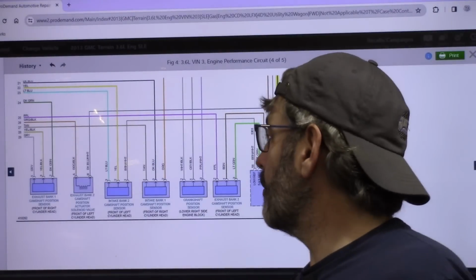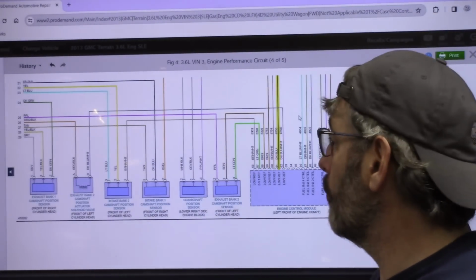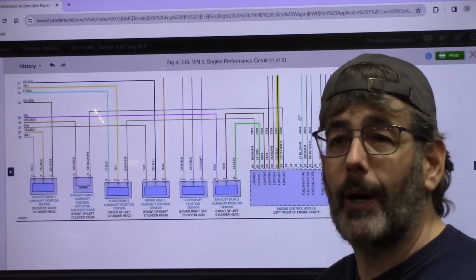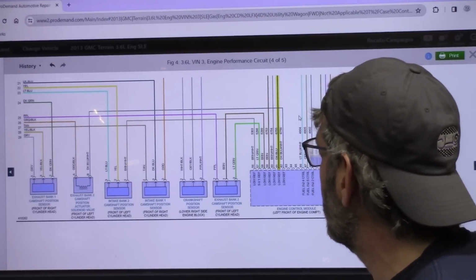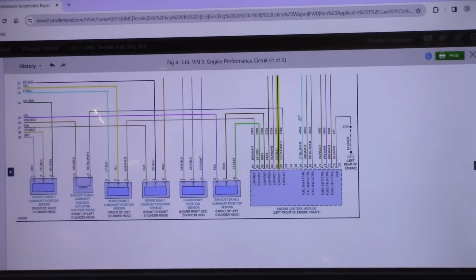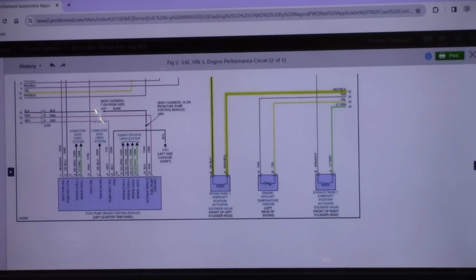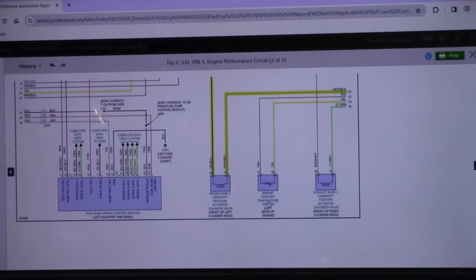All right, no such luck, but generally those VVT solenoids are power side controlled for whatever reason. So if you are working on a car that has one easy to access, there you go. We want to try to find something a little bit easier. Let's go back. It's too bad that that's hard to access because that would be nice. But also the other thing is that it's a solenoid. It's not going to give us the real square wave that I kind of want to see. I want to find something that's also going to give us that nice square wave.